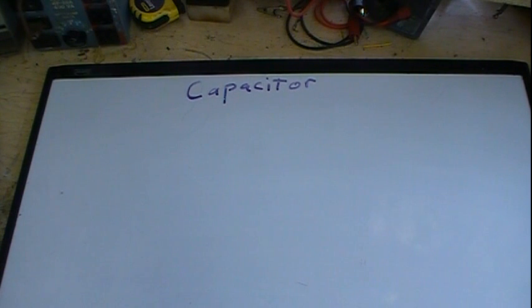Air is about 20 volts per 1/1000th of an inch. So if I have 2/1000ths of an inch, it's greater. Glass, 335 to 2000 volts per 1/1000th thickness, and that varies depending on the type of glass used. Mica, 600 to 1500 volts.